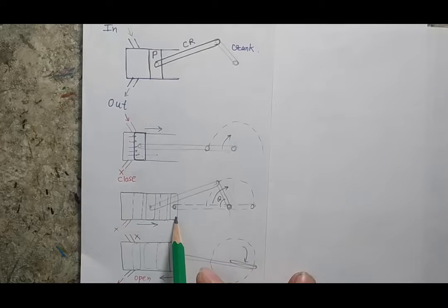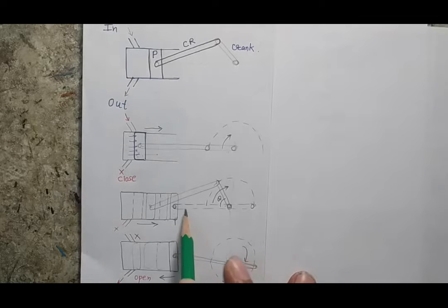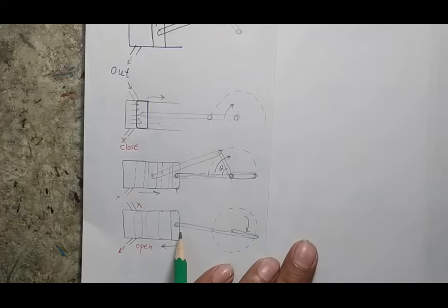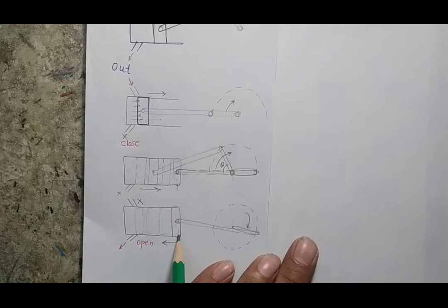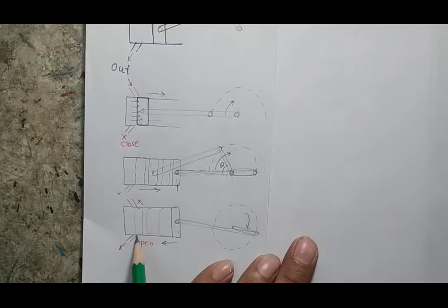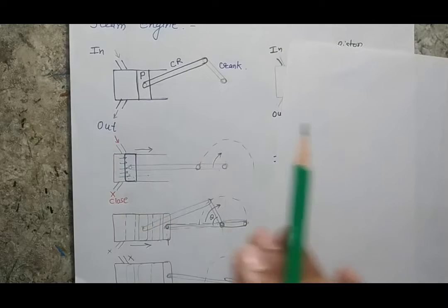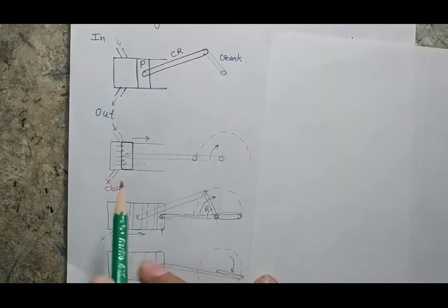So now here I am representing the final state of my piston. When the piston is at this extreme position, this is the orientation of my connecting rod and the crank. When the piston reaches here, again it will move to its original position. While it goes from this extreme position to the other extreme position, whatever exhaust steam remains in the chamber will go out through this exhaust valve. During this period, when the piston moves from its right position to the left extreme position, the inlet valve will be in the closed state. So in this fashion, when the piston reaches here, the inlet valve will open and fresh steam will come inside the chamber and the process will repeat.